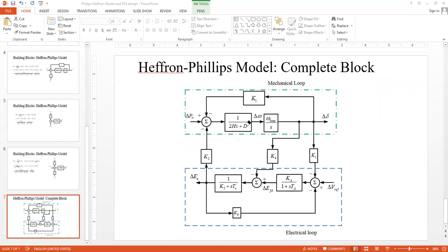So we are not going to reduce this Ka. That could be one solution, but it would take away some of the other benefits that we would have for the system. So we'd keep the same gain value, let's say Ka at 50, which made this system unstable. And remember this summing junction, we would be adding up some del UPSS, which is the same as del VS.